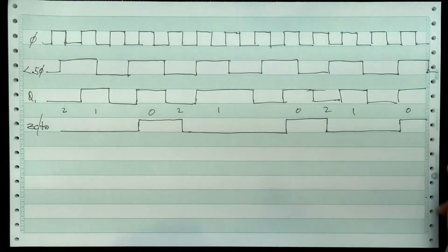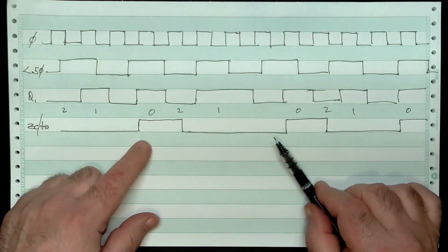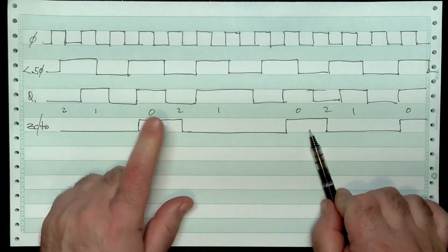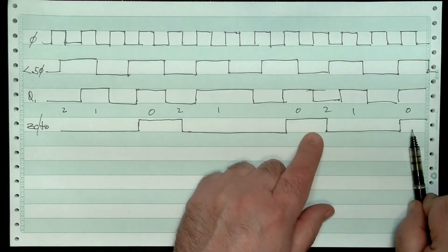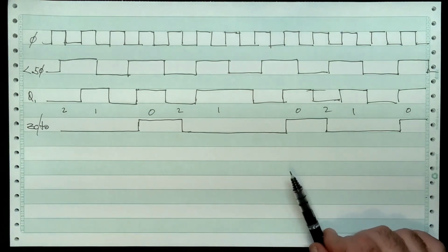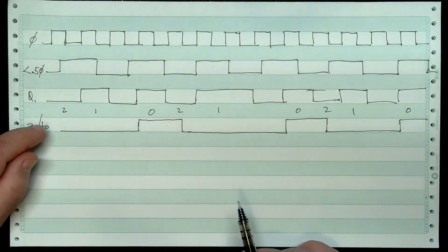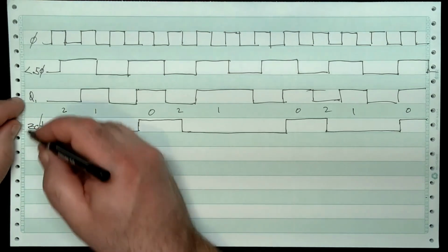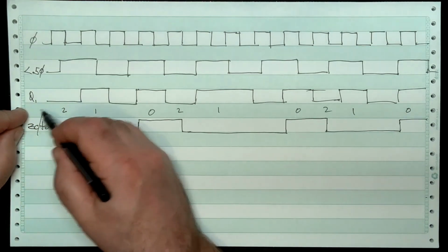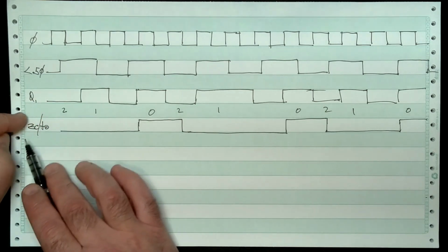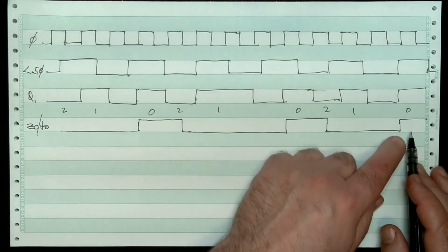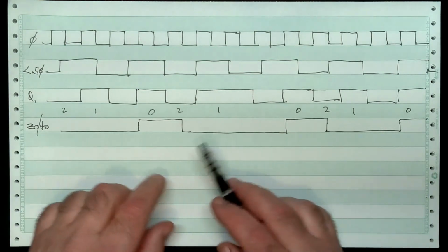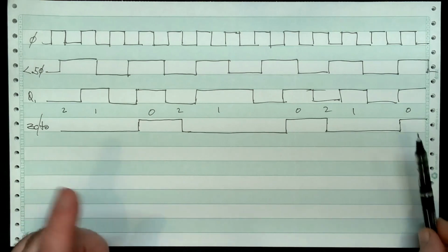So what we got here is, notice that there's a big space between these two pulses coming out of the Z80, and then there's a shorter one here. All right. Presumably, when this was set to a 2, there would have been a 0 that caused this one to be loaded with 2 there. So there would have been a pulse just about over here. So there would be a pulse, and then a near pulse, and then another one far away, and so on. On average, this will be okay. But the point is, it jitters.